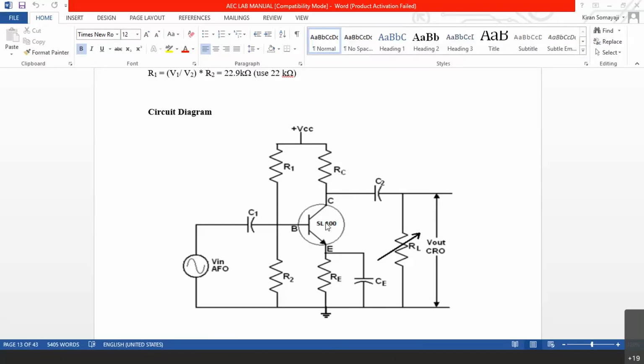Okay, now what you have to do immediately is, right from 0 till let us say around 100 megahertz, keep this input value at around 10 millivolts as an example. Anyhow, when you come to the lab, we will tell you the exact voltage. Otherwise, let us say you are giving a signal of 10 millivolts peak to peak, starting from 0 till let us say around 1 gigahertz. Okay, 1 gigahertz.